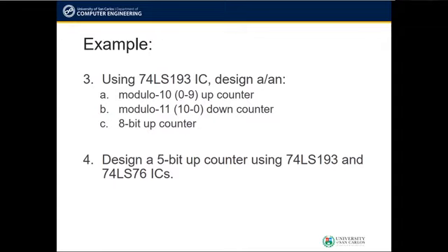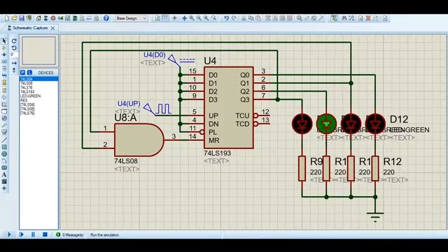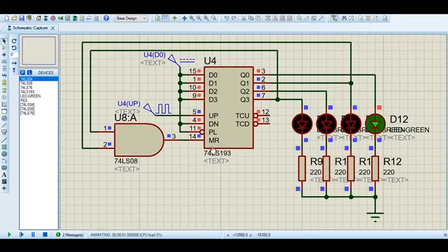Let us show how item 3A here can be implemented differently. The circuit will look like this. Here, instead of checking all the 4-bit output of the counter, only these 2 bits, Q3 and Q1, are checked to see if the count output is already 10.